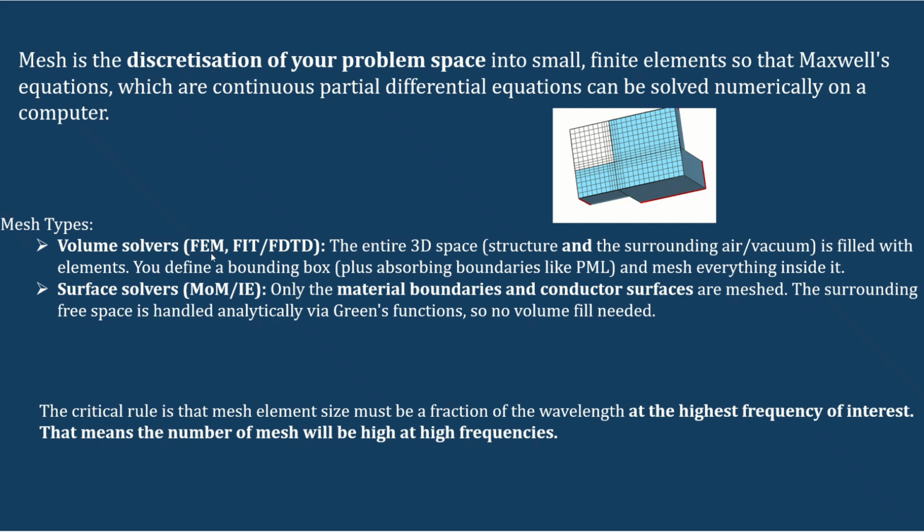If you are going to use any time domain or frequency domain solver, the discretization will be in 3D space. That is, the entire structure will be discretized into smaller cubes or tetrahedral-like structures. If you are going to use surface solvers, only the surface of the geometry will be considered. In that case, we will be using the method of moments and it will be using the Green's function.